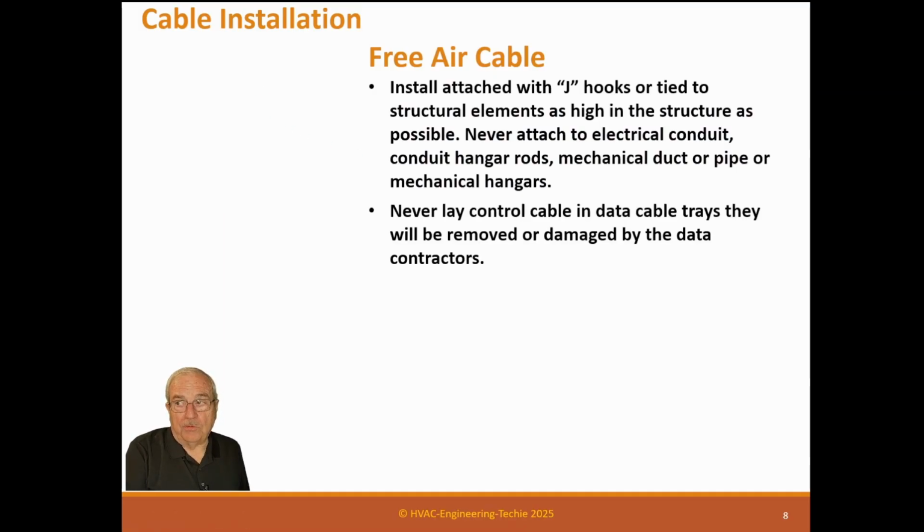Never lay control cable in data cable trays. They will be removed or damaged by the data contractor. Now, I know that sounds like it doesn't make sense because that's what cable trays are for, but it's not your cable. And so you don't want to do that. Your cable will be a different color than the data cable guy's, and those cable trays belong to him, so you want to stay away from those.